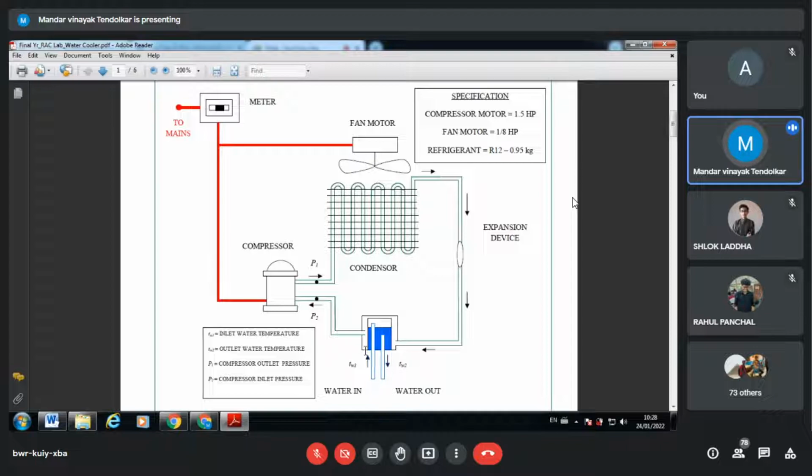Okay. So let's say in the inner pipe there is water, and in the annulus there is a refrigerant, or vice versa, whatever it is. Accordingly there will be a counter flow or parallel flow arrangement, which we will discuss afterwards. This water will reject the heat and the refrigerant will absorb the heat. So water will get cooled. The refrigerant absorbs the heat, becomes hot, and finally completes the cycle and enters into the compressor. So this is how the entire cycle gets completed.